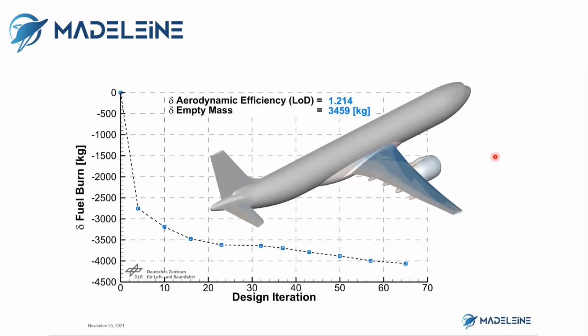We can even use our own model for the structure. What we need for the aerostructure optimization is a parameterized model. And for aeroelastic optimization, we do not need a parameterized structural model. We just need a model, a frozen model, in fact.